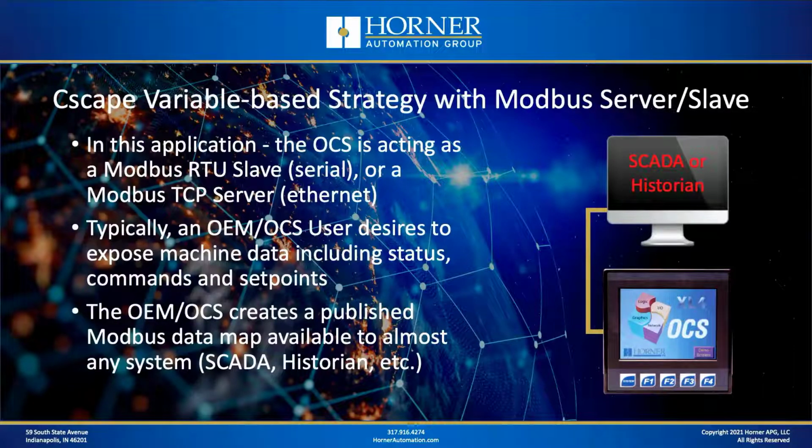So now let's talk about a specific strategy with Cscape. That's the programming package that's designed to configure all aspects of a Horner all-in-one controller. Let's talk about applying an OCS all-in-one controller when it is a Modbus slave or a Modbus server. That's the application where maybe there's a SCADA package, or maybe there's a historian that an end user may want to use. As an OEM, as a machine builder, I want to supply my equipment so that some of the important data that resides in my machine can be accessed by my user and applied with their SCADA package or their historian package, just to name 2 examples.